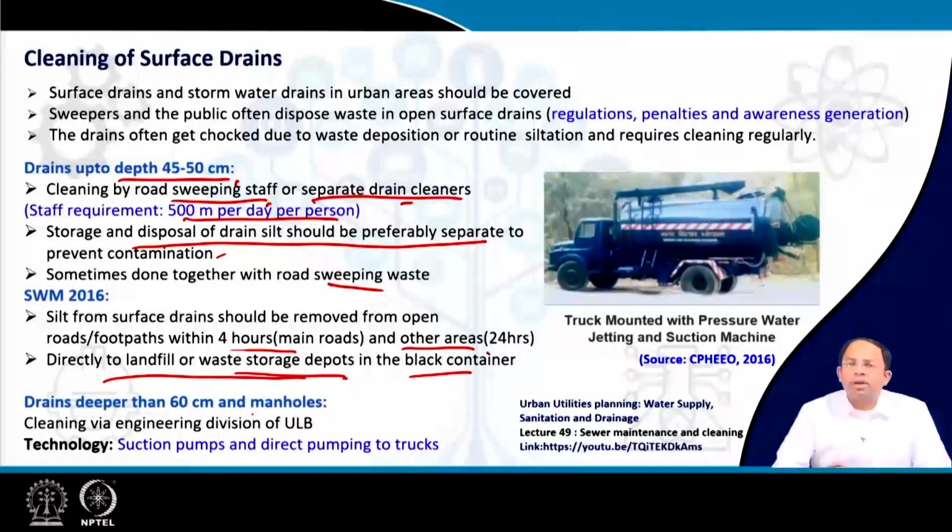And drains which are deeper than 60 centimeters, and even the manholes, cannot be cleaned by road sweepers. So, there we have to deploy mechanical equipment, and it has to be done by the engineering division of the ULB. So, it's a planned service where we use suction pumps and pump directly to trucks such as this, and we can clean the drains by using various mechanical means.